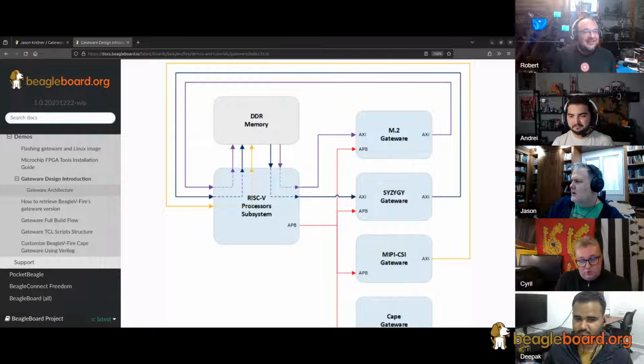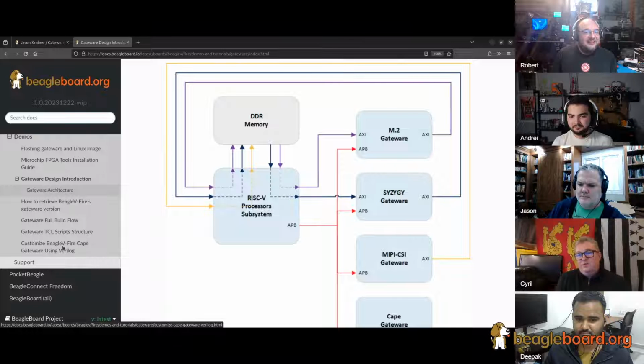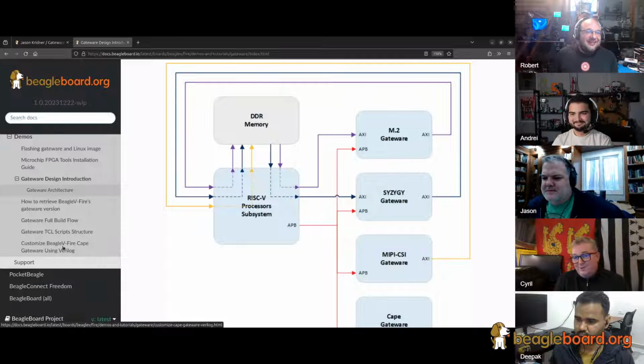I have managed to soft brick myself recently. The easy way to soft brick yourself is to mess up the device tree overlays. The one thing to do is to include the PCI Express block in your device tree overlay and not actually include it in the gateware. When Linux boots up, it goes looking for the PCI Express block and it goes into La La Land. And at that point, we can't get back to Linux.